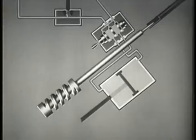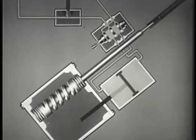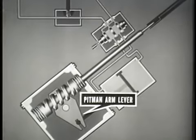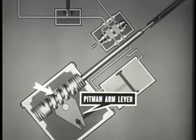The cam is held in center or neutral position by a spring at each end, supported by the steering gear housing. The Pitman arm lever, which actuates the Pitman arm, has one end fastened to the piston rod, the other in mesh with a groove in the steering cam.